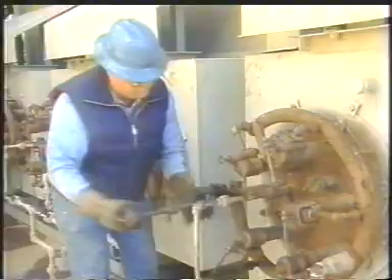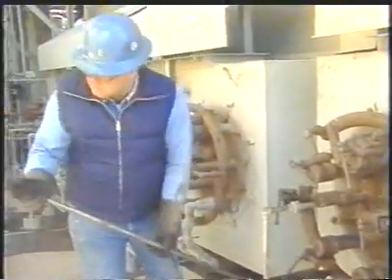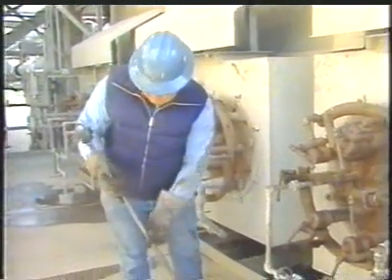The furnace burners can also break down. Burner failures are often caused by plugging or fouling in the burner tip. If a burner fails, you'll need to remove it from service for cleaning or repair.